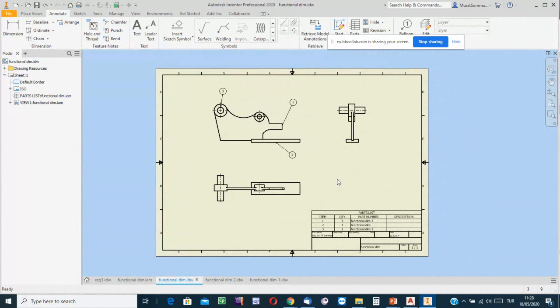In civil engineering convention, there is no ballooning and no parts list. Civil engineers or architects just indicate the component and write a technical note saying that it is, for instance, a brick wall, a door, or a gypsum layer, etc.